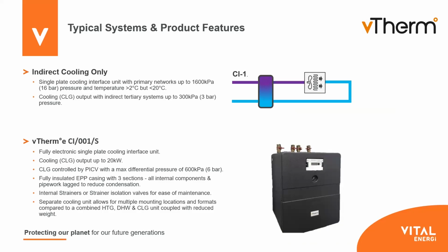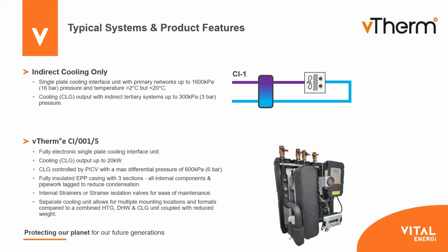And again, these are normally smaller units, and normally you're looking at 10, maybe 20 kilowatts maximum. Again, it depends on the control that you require, and also your differential temperatures with the approaching and offset temperatures. So the cooling is actually quite hard to control, and therefore certain parameters are required.